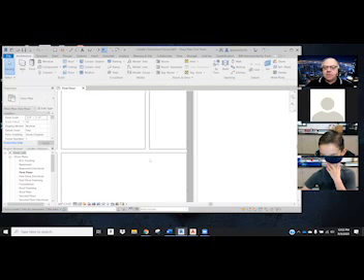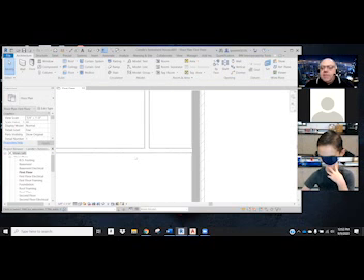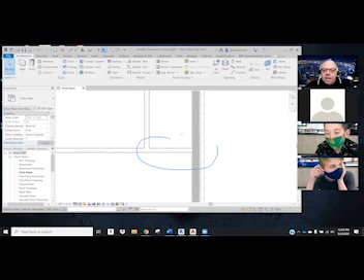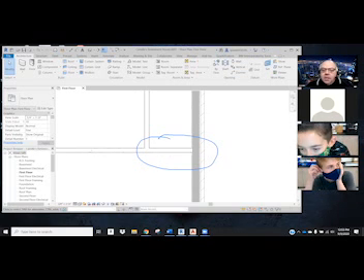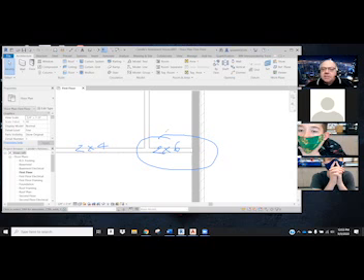Okay, now here's the other thing, and some of you won't have to do this, but I want you to be aware of it. This portion of the wall, and let me bring up my tool here. This part of the wall right here is a plumbing wall. So this is a 2x6. Over here is a 2x4. It's the same wall. I need to change part of it. And so I've got to modify that somehow in order to do that.